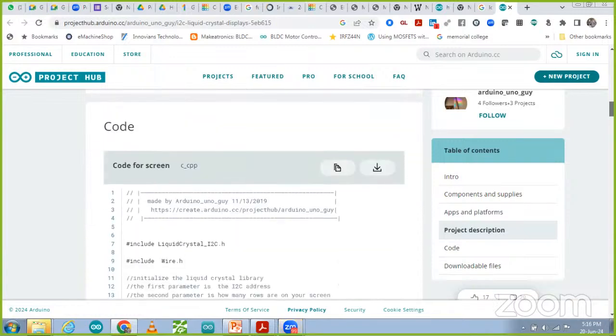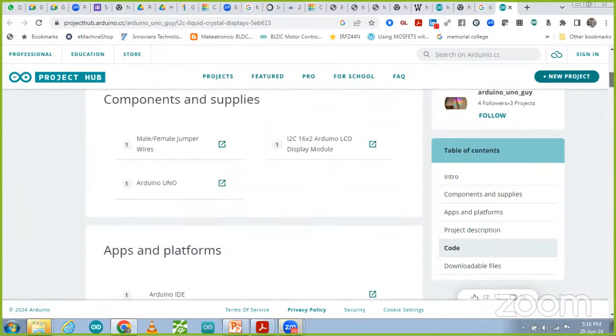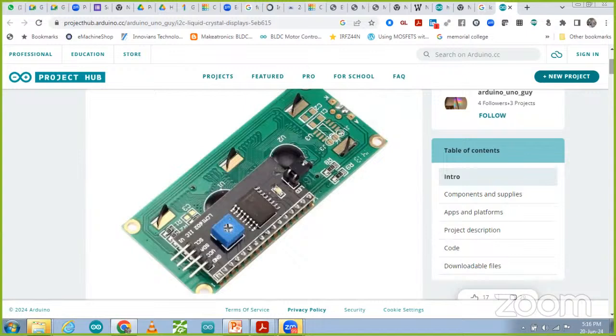So यहाँ पे हमें कौन सा मॉड्यूल लगाना पड़ेगा जिससे कि हम इजीली कनेक्ट कर पाए। This one is the मॉड्यूल, ये आपकी एलसीडी होती है, और this one is the black color module. ये सेपरेटली हमें अटैच करना पड़ता है, सोल्डर करना पड़ता है एलसीडी की पिन पे। And then after that we have to connect 4 pin in the Arduino. Arduino पे हमें 4 पिन्स को कनेक्ट करना है.